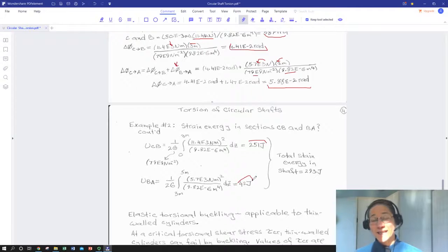Now, nice thing, we only have shear stresses, which don't tend to favor crack opening as much as tensile opening stresses, but they still can propagate cracks. So generally we would use this strain energy as a basis for fracture. If there's a crack in there, we can use the strain energy as a way to say, hey, will it propagate?